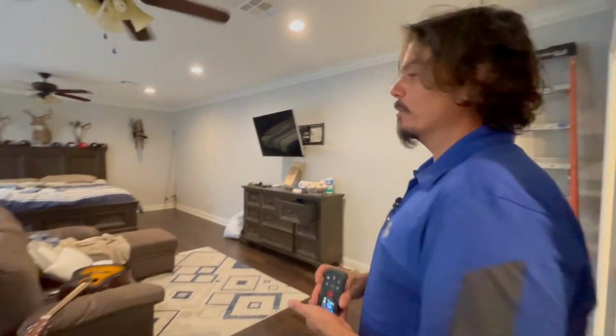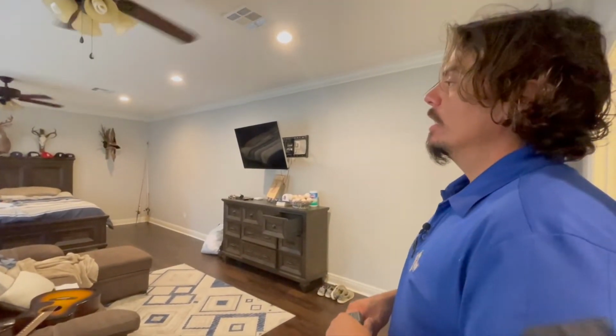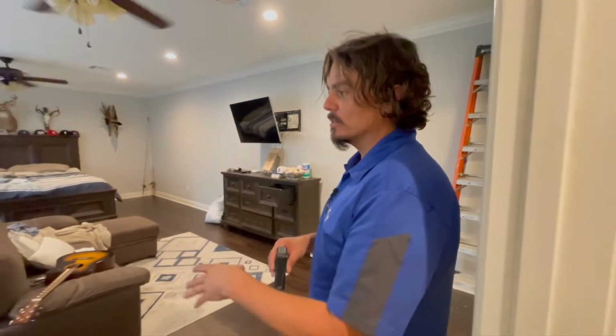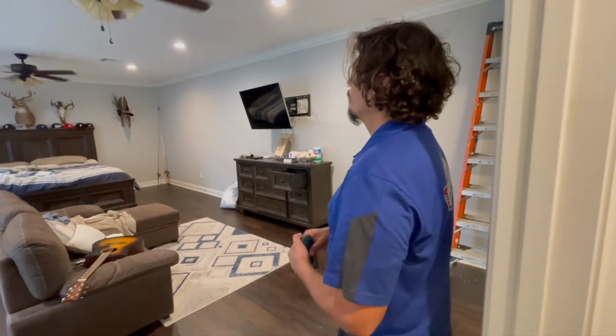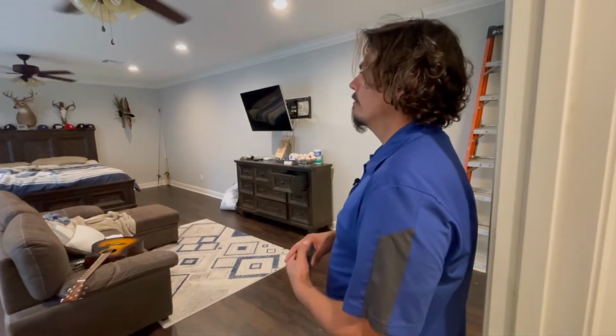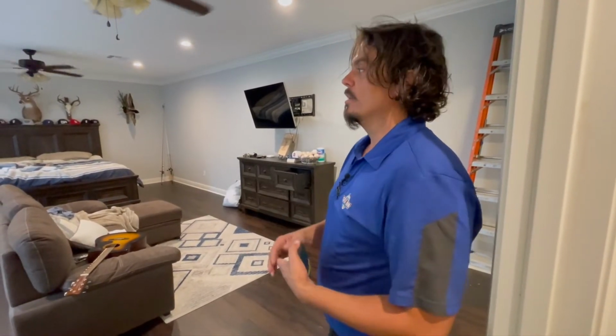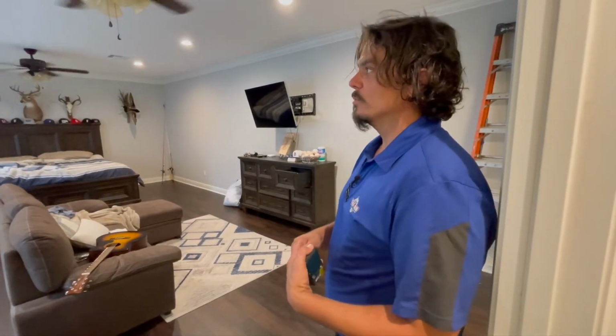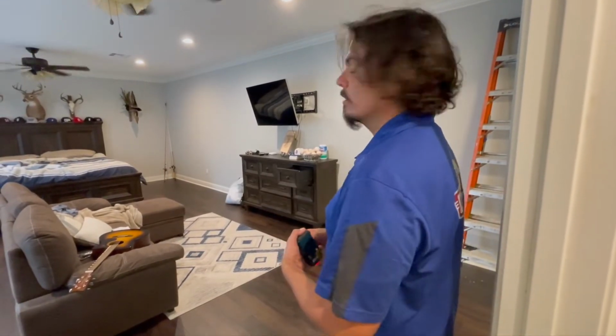You can see the streaking on the door there. So, a frame room over garage, and this is a bonus that was built. And when I say a bonus, they built the garage and the room all at once. It wasn't an afterthought. But this definitely is going to be the area, at least so far that I've walked through, that's going to have the most moisture-related issues. And that could be from the garage, or it also could be some building construction or HVAC related.